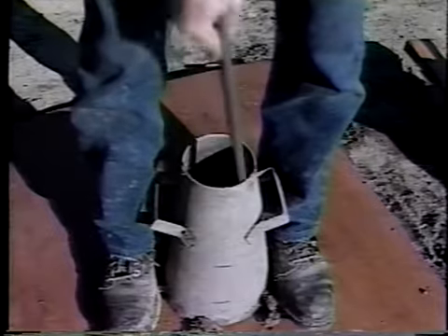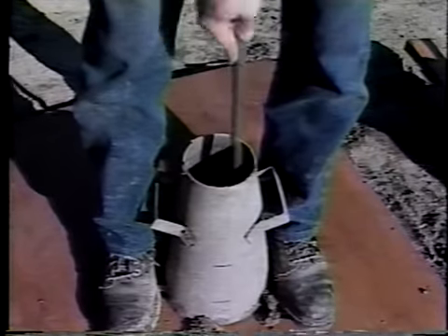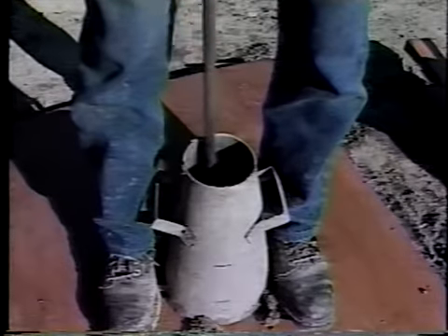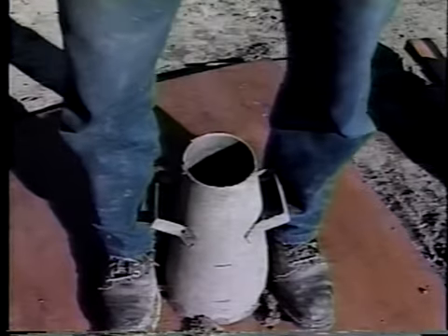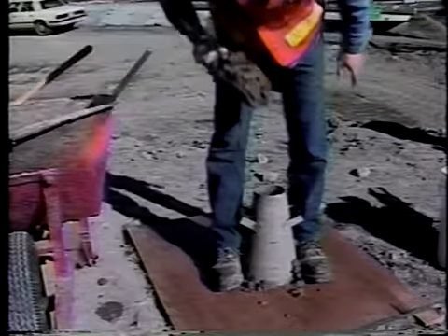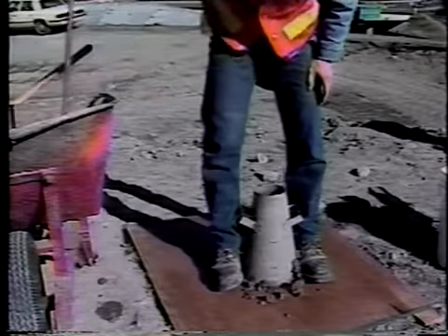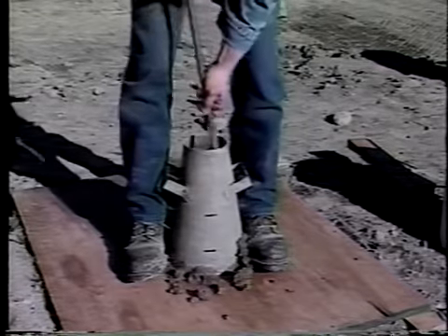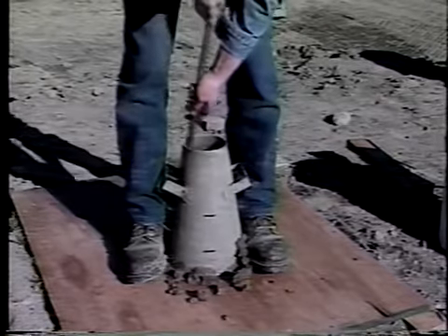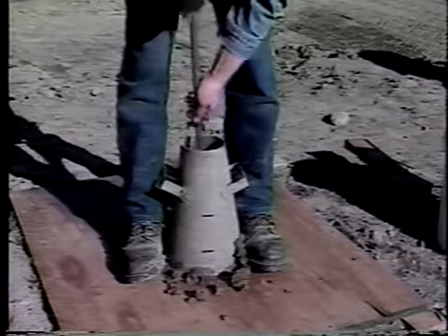A spiraling pattern should be followed as the rod moves toward the center of the cone. The strokes are distributed uniformly. As the rod is moved away from the perimeter, it's returned to the vertical. The second layer fills about half of the cone's height. It's rodded the same as the first, with one difference. The rodding should just penetrate about a half inch into the first layer, not all the way down to the base.